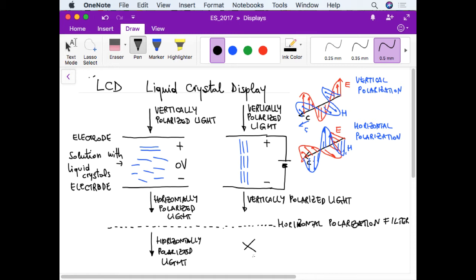The other thing is that typically the light emitted from an LCD display is polarized. In this particular case, it is horizontally polarized, and this is the reason why, for example, if you wear polarized glasses, typically you have problems looking at LCD displays. In my case, I have an LCD watch and I cannot see it with polarized glasses. Or in the car, this typically happens. It is quite common. So, how is this principle used in practice?